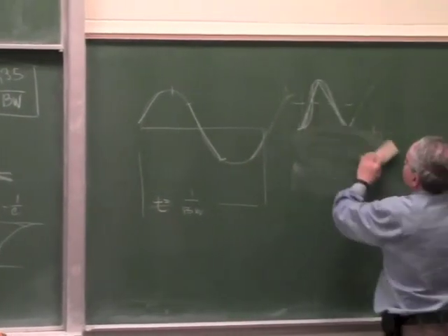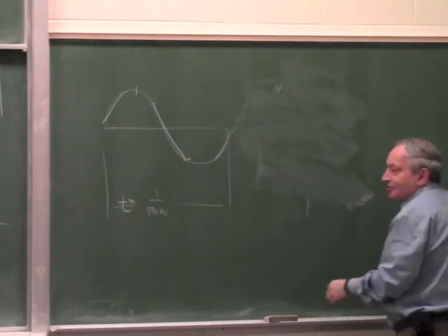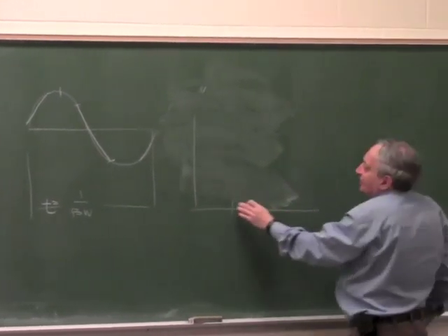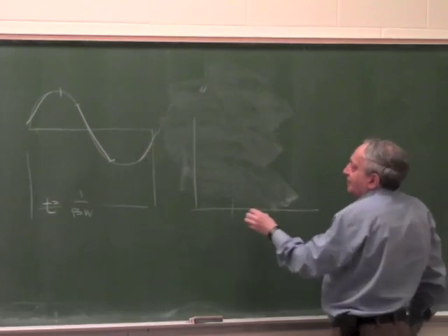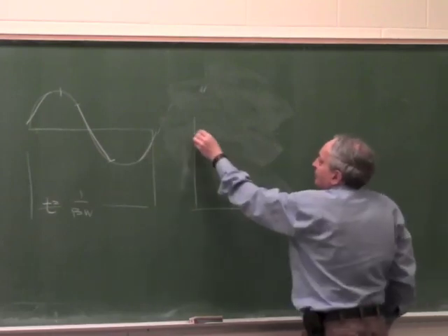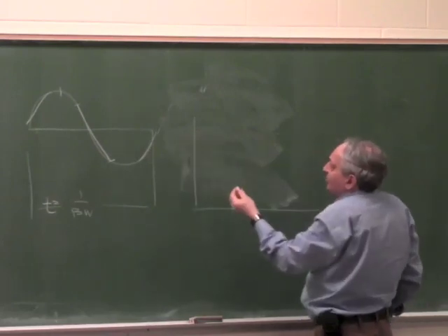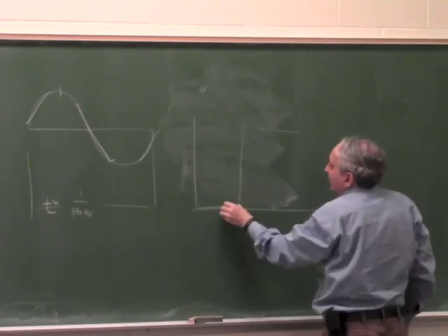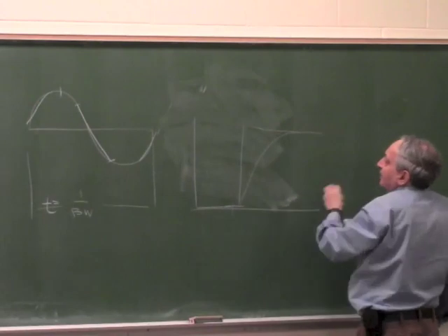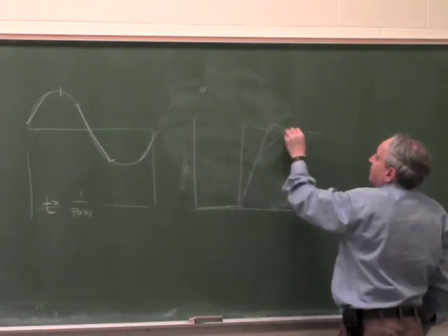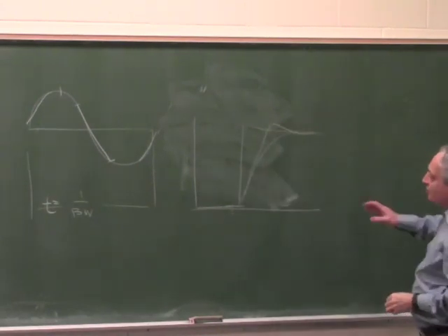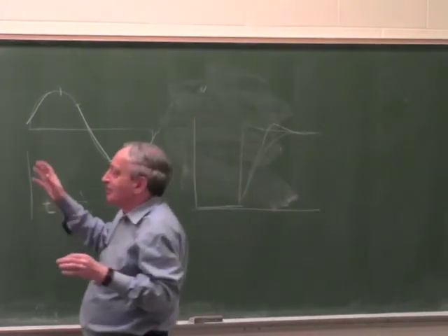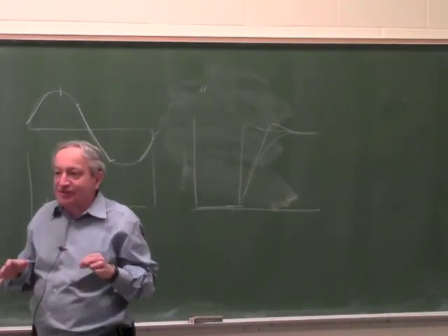But it turns out, if you plot the response of a first order system, a second order system, and so on, the response times are not very different. So if I plot here the pulse responses of different systems, if I have an RC system, the pulse response will look like this. If I have a second order system, maybe it will do like this. But in general, it's a very rough rule of thumb. Remember, that's not a mathematical proof, that's just a rule of thumb.